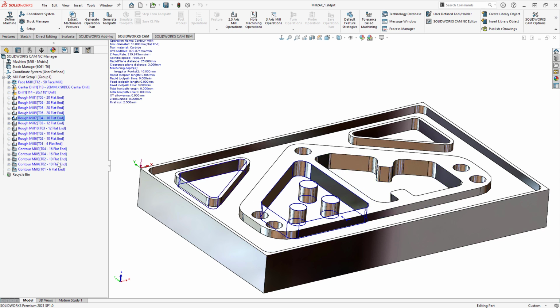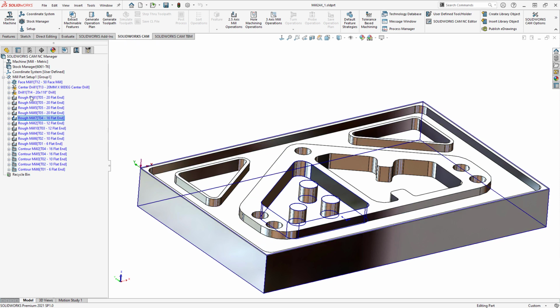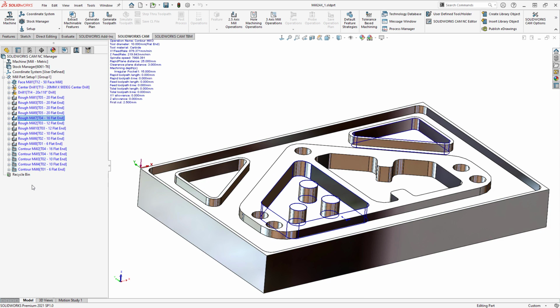But what we've done here at this point is we've segregated out the tooling size itself so that now it doesn't have to switch out tooling between every step. And then we've also done the fast operations down to the slower operations with the holes on top. It's something that's pretty quick and easy, and it's able to get in there and get this exactly the way that you want it. So now that we have everything organized, and I did this organization first because the next step is to actually generate the tool path.